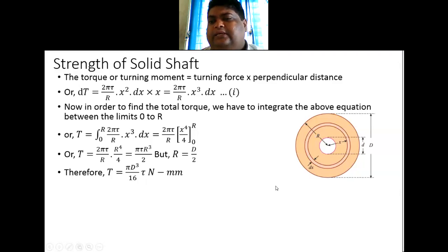That is one reason. Another reason is the rigidity, sorry, not the rigidity modulus. The rigidity or the strength of this hollow shaft is comparably higher than a solid shaft for the same weight to length ratio. For this reason, in many applications we use hollow shafts.